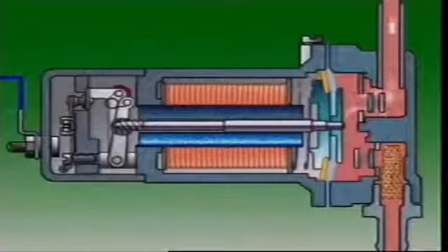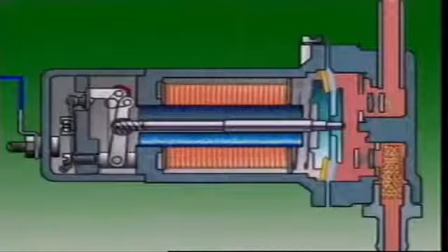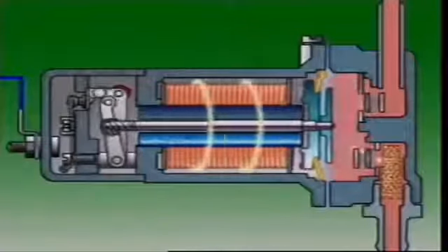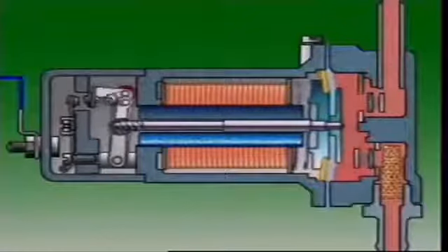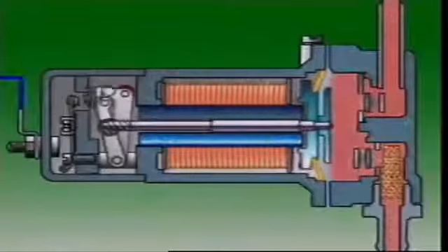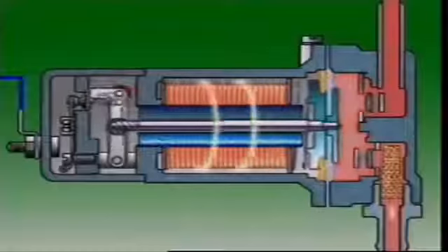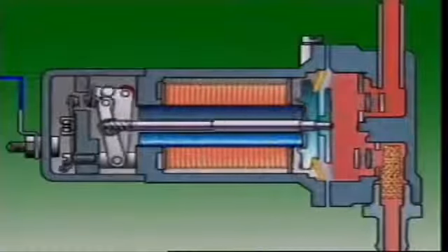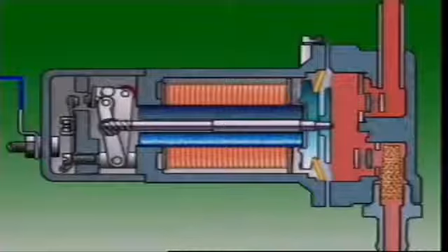The armature is released, and the diaphragm spring forces up the diaphragm, which forces fuel out of the pump and on its way to the carburetor. This action continues, delivering fuel each time. When the engine needs less fuel, pressure builds up in the fuel lines to the carburetor and reduces how much fuel is delivered. Some carburetor-equipped vehicles with electric pumps have a safety switch that prevents the pump continuing to run if the engine stops.